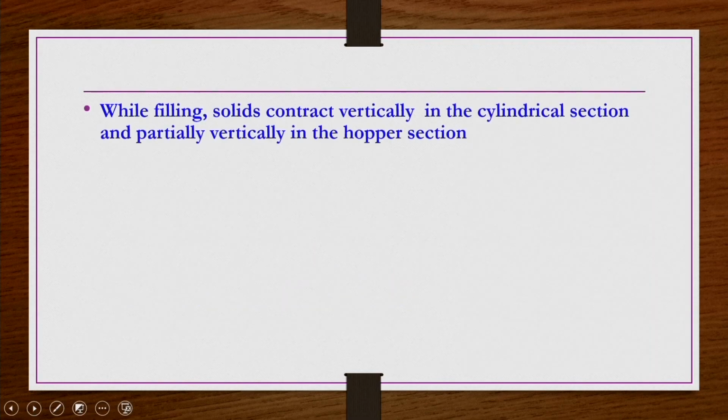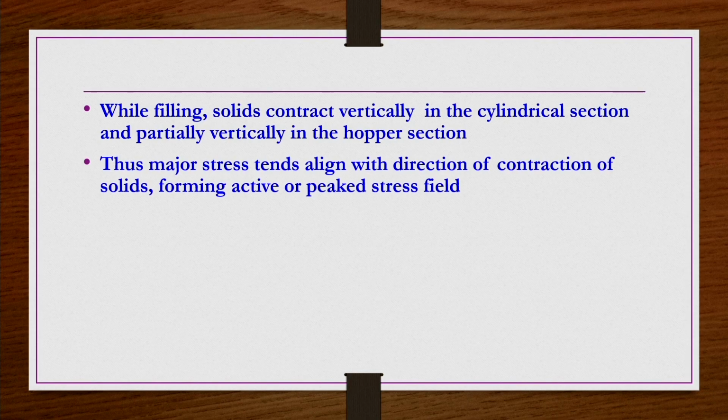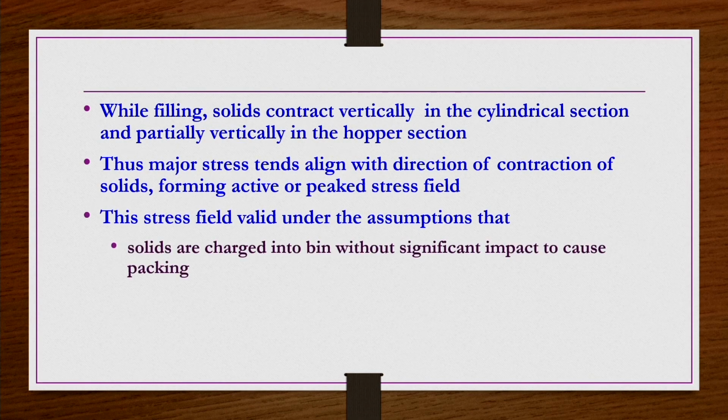Okay. So, while filling, solids contract vertically in the cylindrical section and partially vertically in the hopper section, that is the conical section at the bottom. Thus, major stress tends to align with the direction of contraction of solids, forming an active or peaked stress field, and this stress field is valid under the assumption that the solids are charged into the bin without significant impact to cause packing.